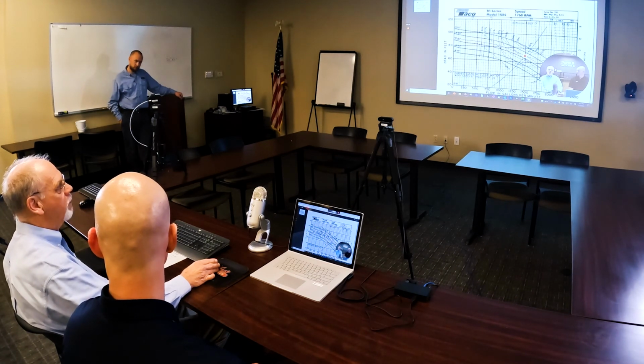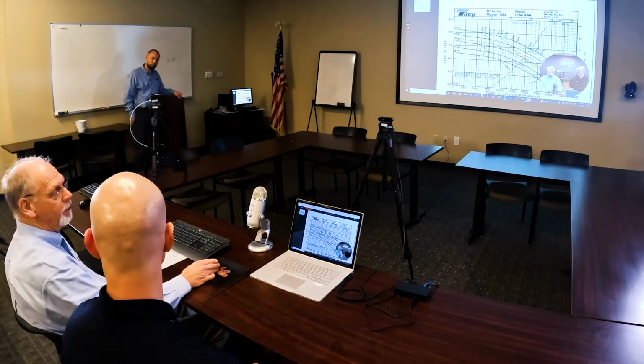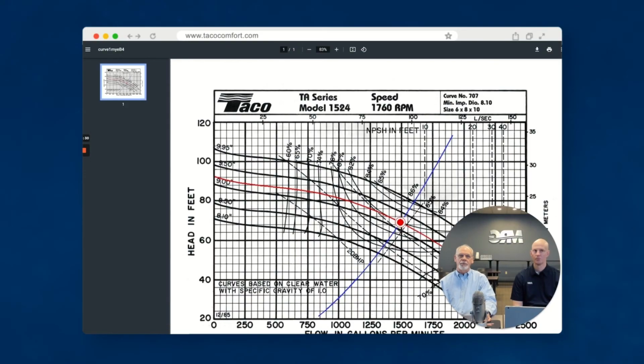And you can have one too big and you won't get the pressure drop through it, so it's not going to be as accurate to get the flow. So there's a lot of things that go with the pump with the accessories, and you can take that and help the contractor with his piping arrangement at the pump with your pump, your suction diffusers, your flex connectors, and your triple duty valves.